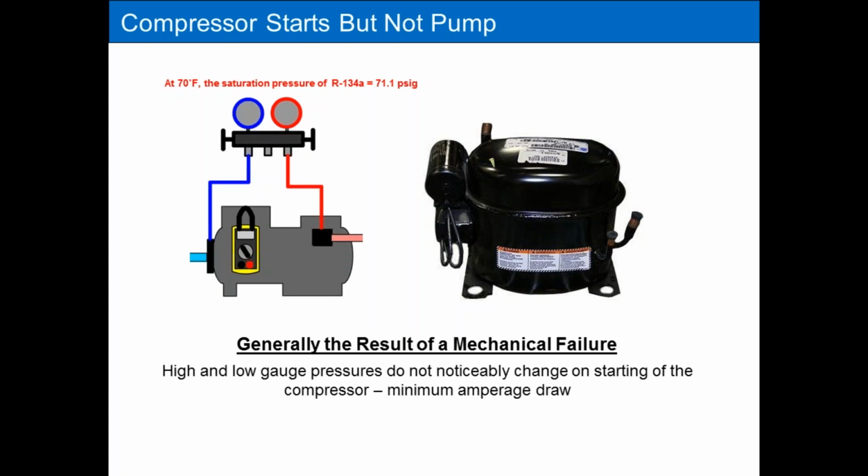So the next step is you plug the compressor in, turn the unit on and see what happens to your pressures, even though they're low at this point, right? You know that it's lost refrigerant, so that's part of the problem. But you still want to see if that compressor has the ability to pump. So you plug it in, turn it on, and you want to see your low side pressure drop and your high side pressure go up. Now I can't tell you where they should go because the pressures are going to be wrong, but you want to see a change, right?